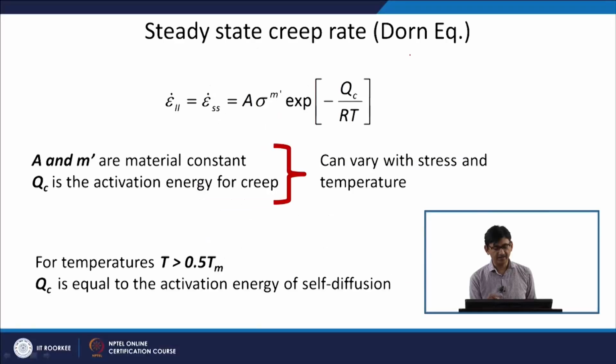So, as I told you, this second stage is of importance to us, because that is the stage which covers the longest time in the creep curve, and the material will undergo this second stage for the longest time. So, we want to understand and characterize or quantify that particular stage, to understand the creep phenomena.